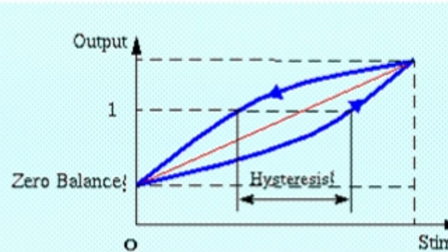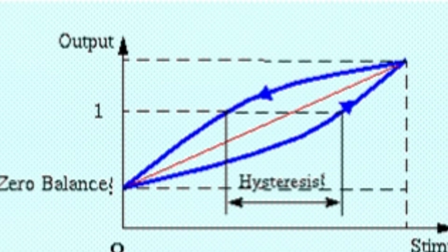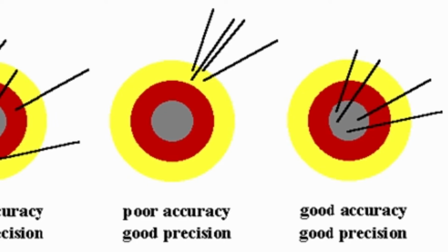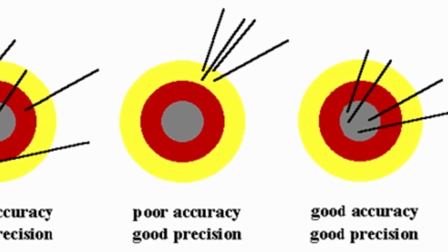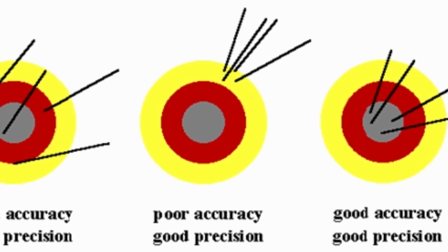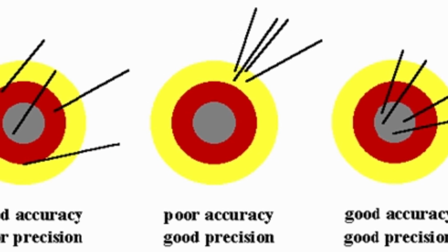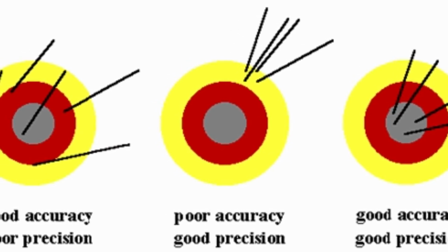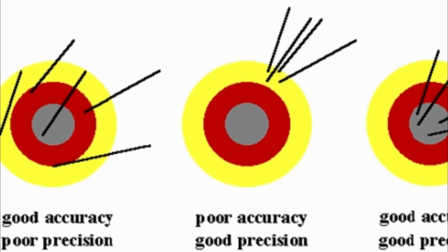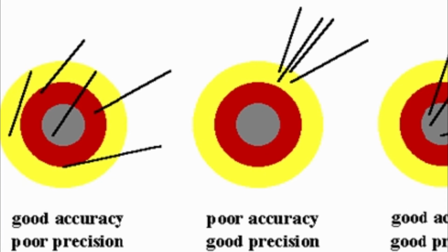Calibration. If a meaningful measurement is to be made, it is necessary to tune the output of the sensor with accurately known input. Full-scale output. The full-scale output is the difference between the output for maximum input and the output for minimum input. Based on this, the ADC's reference voltages have to be selected properly.